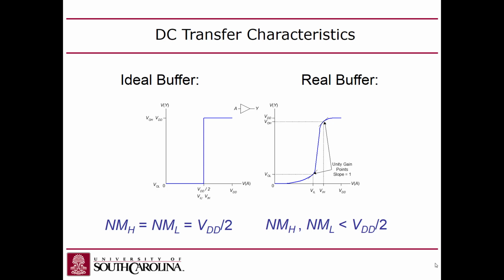But as it goes into this gate, the gate sees that 300 millivolts and says, well, you're below VIL, so my output is going to be, in this case, because it's an identity function, lower than 300 millivolts. The output might be 100 millivolts or 50 millivolts, right? So the gate fixed the signal, basically. It conditioned it. And that's what's happening here.